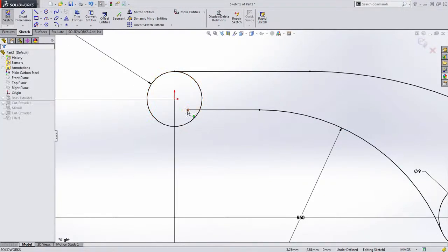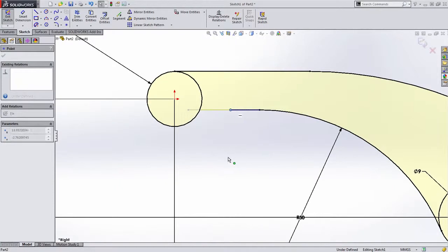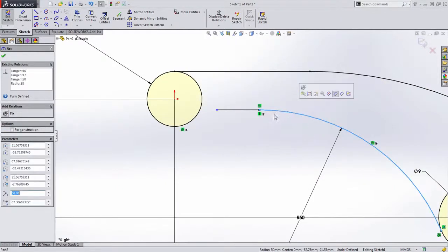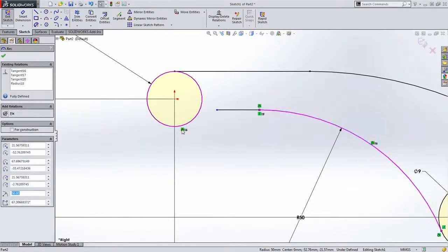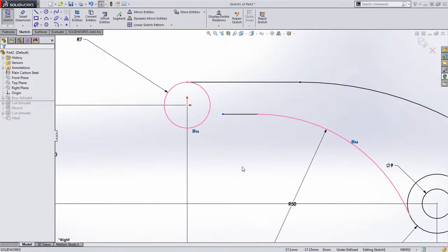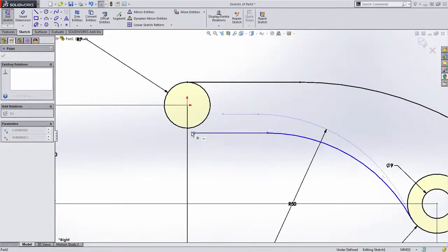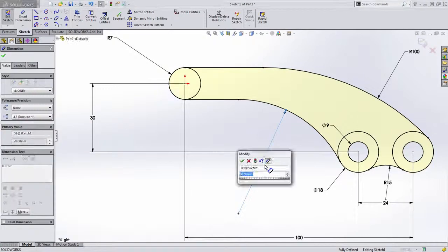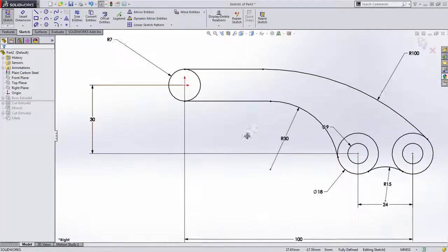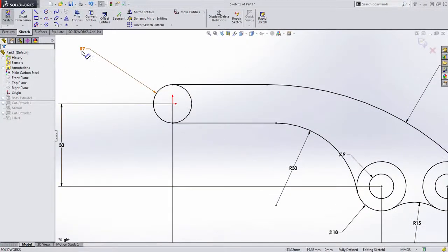But you'll notice I can't actually go through the process of adjusting this line. And the reason is because even though I trimmed that arc, this tangency relationship, not that one, this tangency relationship is still locking this arc to this arc here. We'll go ahead and delete that. And notice once I do this, I can just move this and snap this to the bottom of the arc. We do need to change the radius of this arc as well to 30 millimeters, and notice this subtle change.